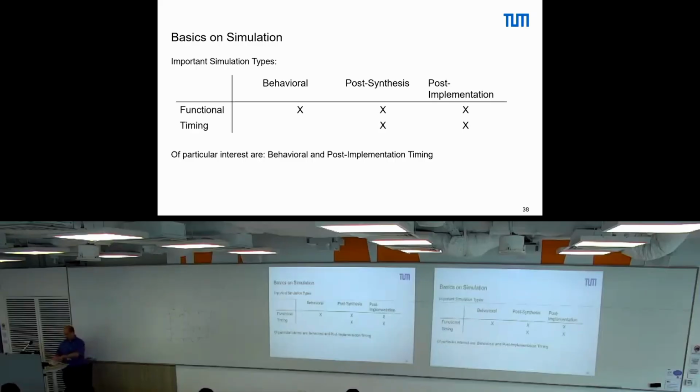The one, probably simpler one, is the one from the clock. So we start effectively at some common node, and get a timing here. I write it capital T clock, not to mix up with the period length of the clocks, but the clock path length.